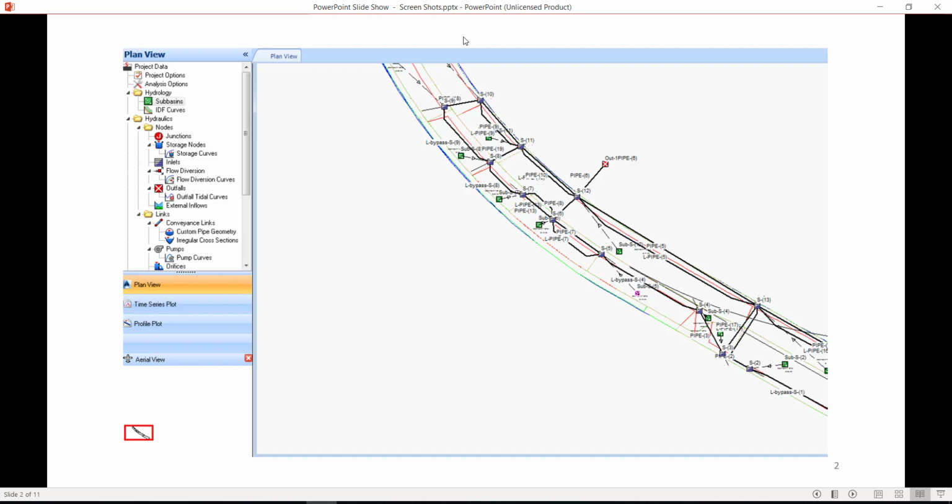The key areas of the plan view include the location of drainage network elements, and the distances between them do not have to conform to the actual physical scale. They can represent a schematic diagram of the network. Elements can have their properties, such as flooding depth at junction nodes or flow velocity in channels and pipes, displayed using different colors. This color coding can be controlled using the displayed legend.